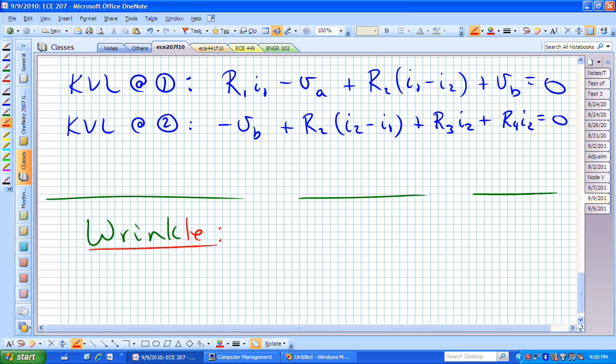So if it's an equality sign, we have to be compatible. Meaning if you have a voltage on the left, you have to have voltages on the right. If you end up with a current on the right, there's a problem. Does that make sense? And if you're writing nodal analysis or equations involving nodal analysis, then if you're dealing with currents, if you're having currents on the left, you better end up with currents on the right. Everything has to be compatible.